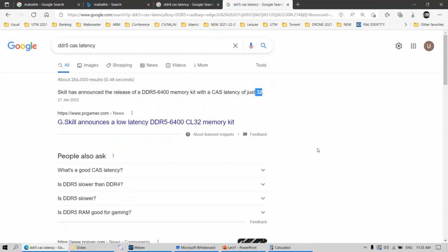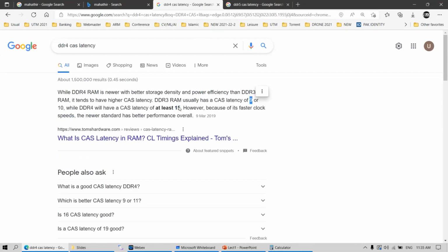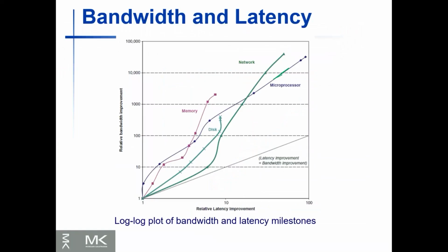But actually, if you calculate this, if I'm not mistaken, last time I did some calculation between DDR3 and DDR4, the improvement in terms of latency after including clock rate, of course, you can see the latency is becoming worse from 9 to 15, but including the clock rate, this is running at 2.4 gigahertz. This is running at, I don't know, 333 megahertz. I don't quite remember. If you calculate again, then you'll realize it's the same. It's not much difference in latency. So latency is not much improved, but the bandwidth is improving. I can still transfer a lot more data.